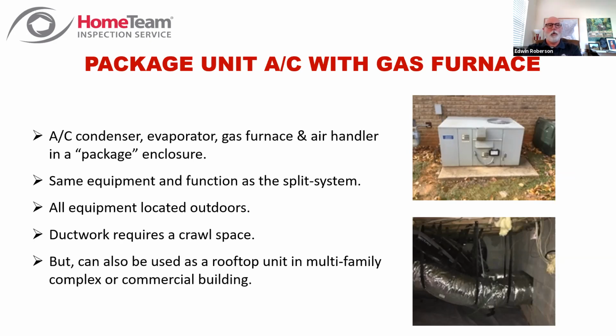Easy to do, set the equipment outside. And that ductwork does require a crawl space, or occasionally you'll see someone who will run a duct from that up the sidewall and into an attic. I guess if you go far enough back that you've got a house on a slab that didn't have central air and you want to add central air, that's kind of your only way.